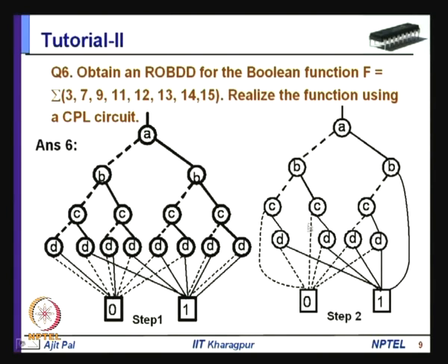Then similarly, this dotted line from C will come to 0. Then this, and similarly these two, will also disappear. So, this dotted line A, B, C. So, 1, 2, 3, 4. Actually, this entire part has been removed, because you can see this will merge and this C will also be redundant. So, this B solid line has come to 1 as it is shown here. So, in this way, in the first step, this much of minimization is possible.